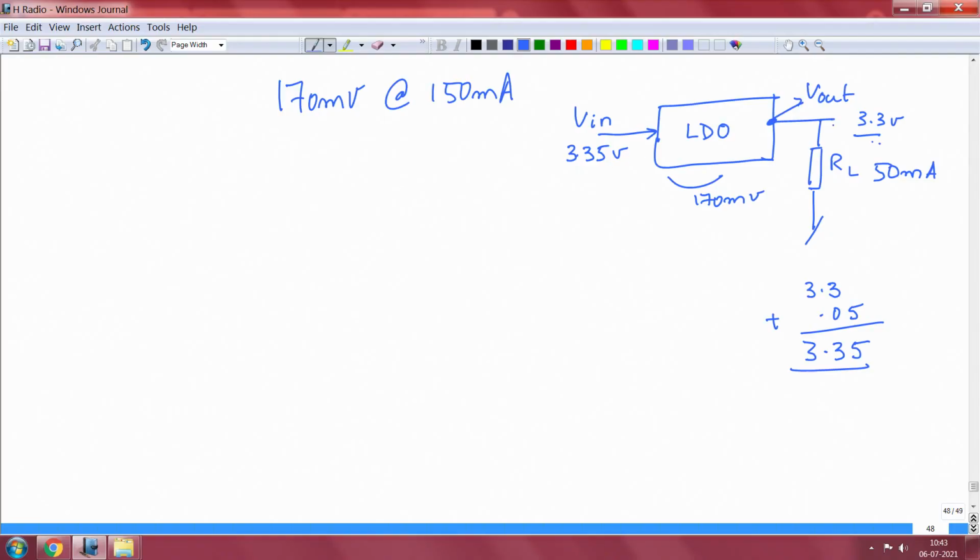Okay folks, welcome back. You recall this picture we drew about the input versus the output voltage. So very close difference between the input and the output, and at extremely low load currents the drop can be very low, right. So you want 3.3 at the output, you can just feed 3.35 volts at the input and then you can just drop a very small voltage across the LDO and beautifully it will still regulate the thing. This is something which is revolutionary as far as the voltage regulators are concerned.